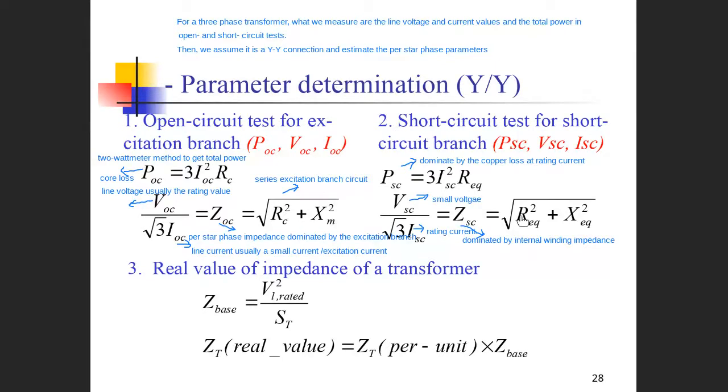So in the equivalent circuit, both sides will be 10 ohms and 10 ohms. In practice, when you measure the primary, it is 10 ohms, and the secondary, when measured, is 0.1 ohms, times 10 squared, that's 10 ohms, right? That's the meaning of it.